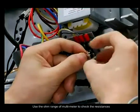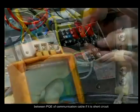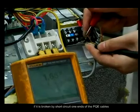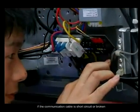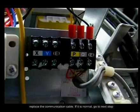Use the ohm range of the multimeter to check the resistance between P, Q, E of the communication cable to see if it is short circuit. Check if the communication cable is broken by short-circuiting one end of the PQE cable. If the communication cable is short circuit or broken, replace the communication cable. If it is normal, go to the next step.